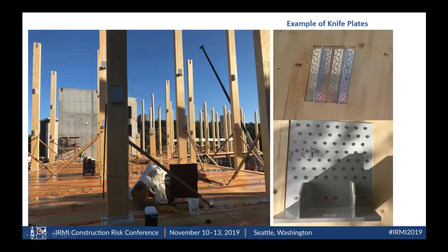In hindsight, what it should have been is a knife plate from concrete to wood or wood to steel, but not wood to wood. We could have done the dovetail and made it a lot easier and shipped it and not had to have these connections done in the field. But I made the call after seeing them months late. Instead of going through a redesign process, we sent them to us and put all these on in the yard.